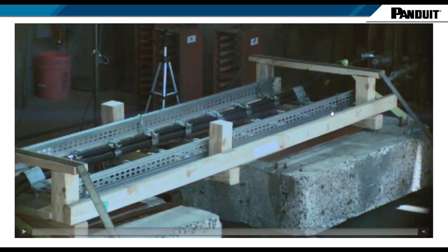If it's all good, if it's a successful test, the cleats are still there, no damage to cable, we do not tighten anything up, we don't adjust anything, we go back to the control room, hit it again with a second short circuit of the same level, and again, no loose or missing parts, no damage to cable. If we pass that, we take the rig away from the connection, we spray each cleat for 2 minutes with water, we then apply a voltage withstand check for 2 minutes.